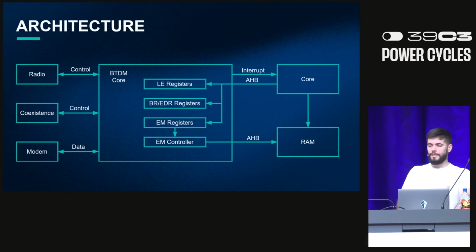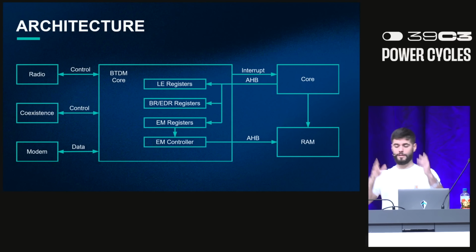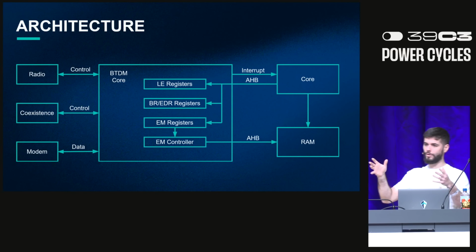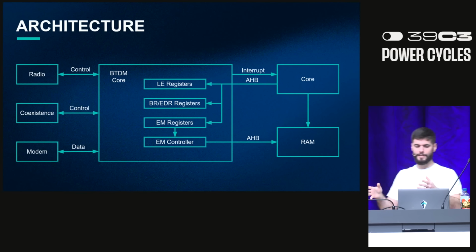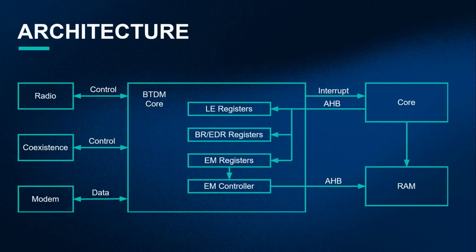We found a fairly complex Bluetooth peripheral architecture. On the left, in the middle, there's this Bluetooth dual mode core block that talks to other peripherals that have hidden buses that I don't think we can see. But we know they're talking in between for the Bluetooth to be able to send and receive messages via radio frequency. And then this Bluetooth core communicates with the main core via 3 main mechanisms.